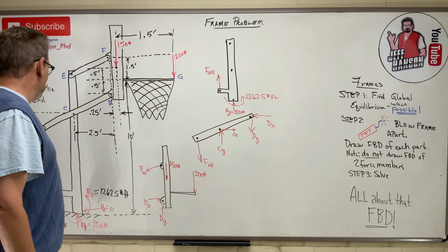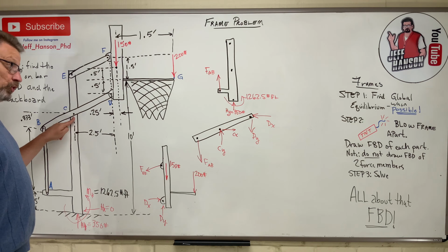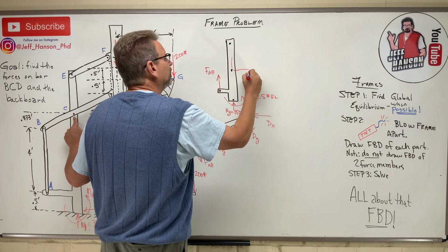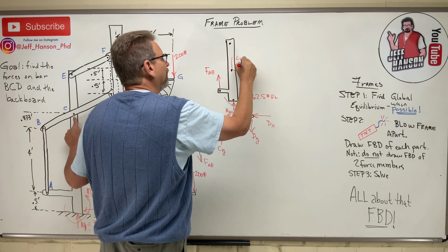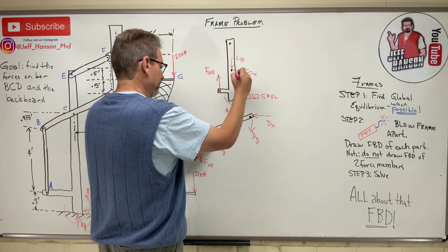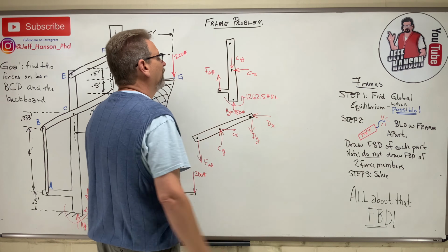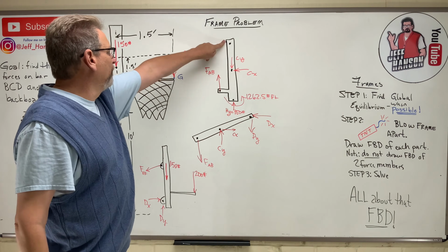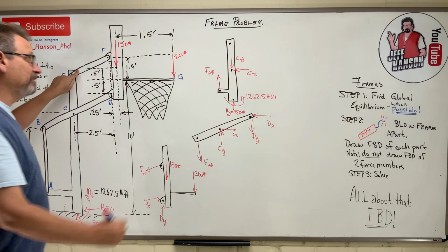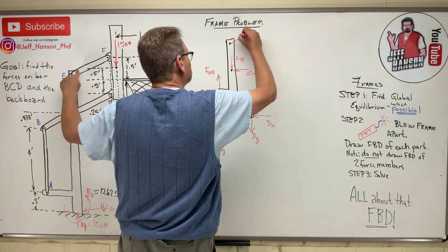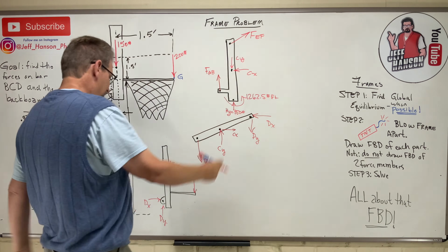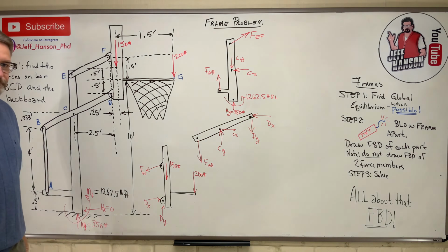Okay? And then in the middle here, boom, that's joint C right here. We already know what he is. He's a pin connection, CX, CY. And we know these directions. So now I know these directions, right? He's got to go that way and that one's got to go that way. And then finally I've got one more at the very top, and at the very top is joint E. This guy was in tension. And so guess what? FEF and that guy are the same.